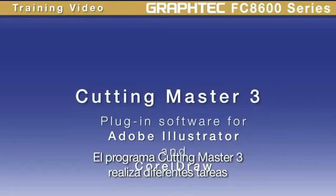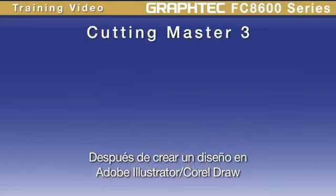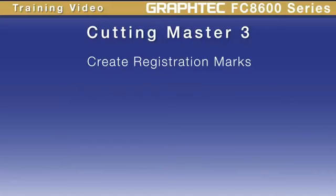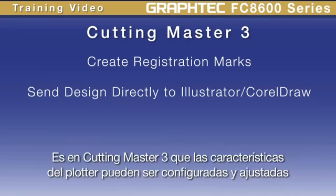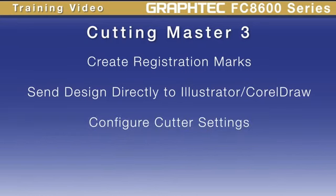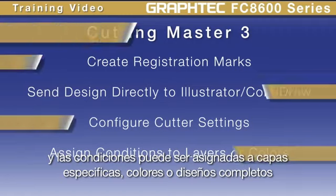The Cutting Master 3 application does several tasks. After creating a design in Adobe Illustrator or Corel Draw, registration marks for the print and cut process can be placed on the job design. The design can be sent from Adobe Illustrator or Corel Draw directly to the Cutting Master 3 application through the special GraphTech plugin that is added to Adobe Illustrator and Corel Draw. It is in Cutting Master 3 that cutter settings can be configured and adjusted. And conditions can be assigned to specific layers, colors, or whole job designs.